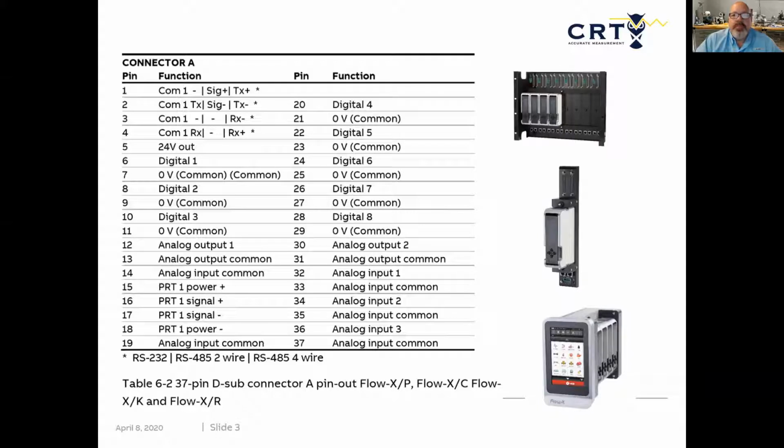the type of base that you use. The inputs that we have, the 16 digitals, the 6 analog inputs, the 2 RTDs, are the same as far as the number that we have and the way that they're configured in the software. But what's different is, depending on the base that you're using, where these are landed.